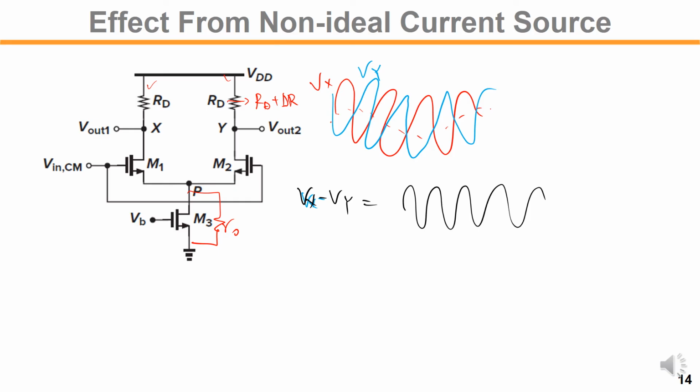Why? Because for input common mode variation, current will be split onto both branches, so I0 over 2, will see both current, but this current is modulated. So this one is small signal sense. The voltage drop over RO would be V_in,CM. Thus that one would be current level V_in,CM divided by RO.